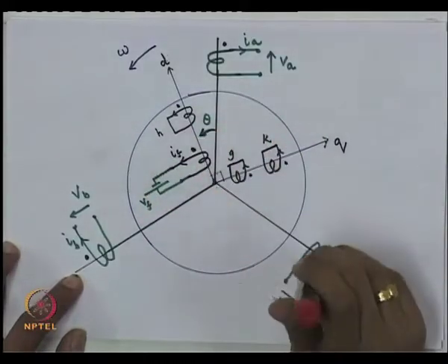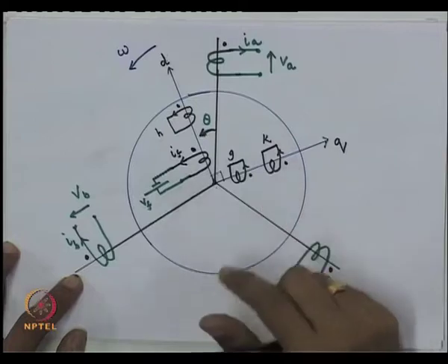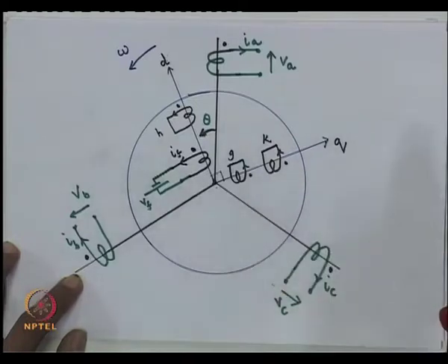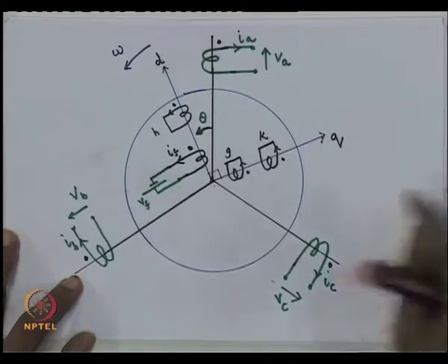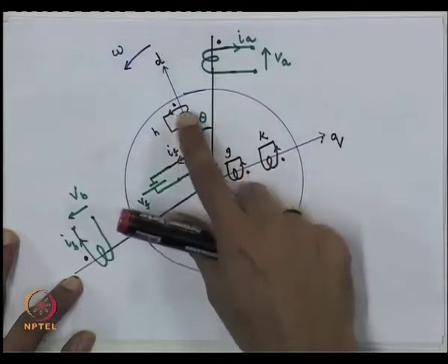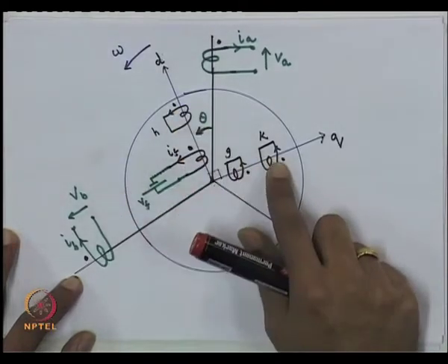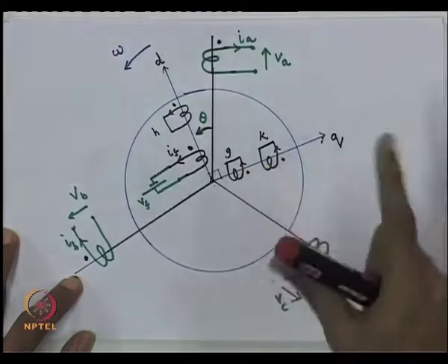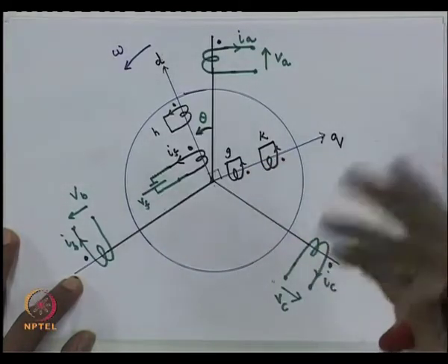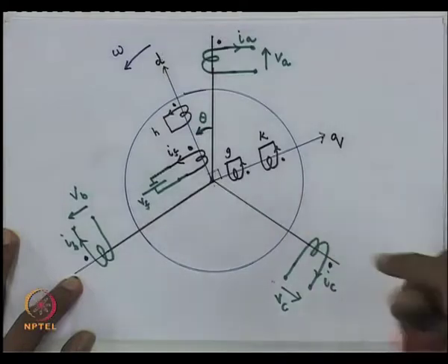This is an assumption in the sense that somebody may say you can have more. The answer is yes, you can have more, but often it is seen, as far as steam turbine driven generators are concerned, that you require these many windings and their parameters to represent the kind of dynamics which you will see from actual measurements and observations in actual tests.